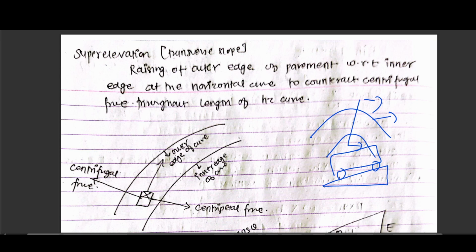What would this kind of shape do? This kind of shape will counter the vehicular centrifugal force. The centrifugal force acts in the horizontal direction, and it would be resisted by a lot of components. If we provide it like this, then there will be an inclination, and W will be there, and its component will be there, and the P will also be divided into two components, so that's why the P force, the centrifugal force effects, will also be divided.